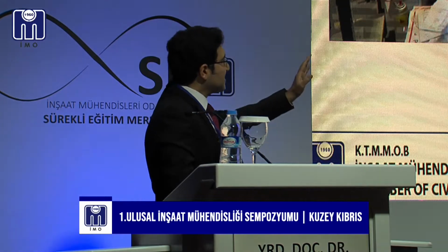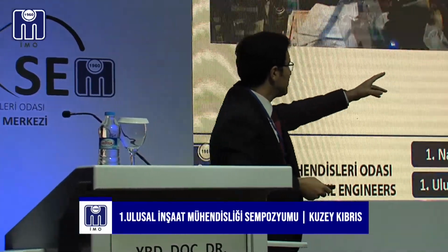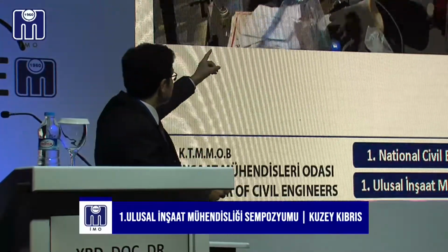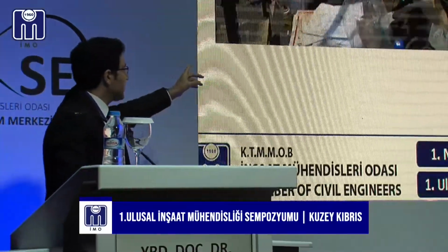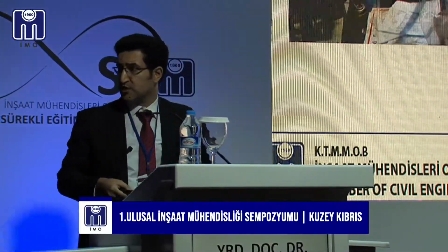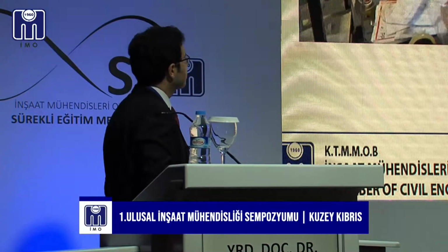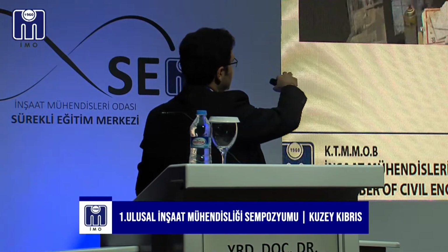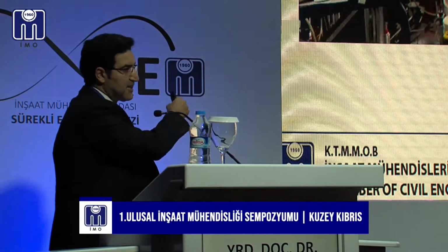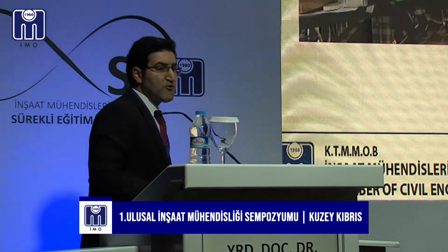This is the range of sample sizes at Kiso-Jiban company, from 5 centimeters to 30 centimeters. This is the typical cyclic triaxial test apparatus, but this one is very interesting to me as well. This is the biggest cyclic triaxial apparatus I have seen, at Kiso-Jiban: 60 centimeters in diameter and 60 centimeters in height. They got a project from Australia and used it to calculate the liquefaction resistance.